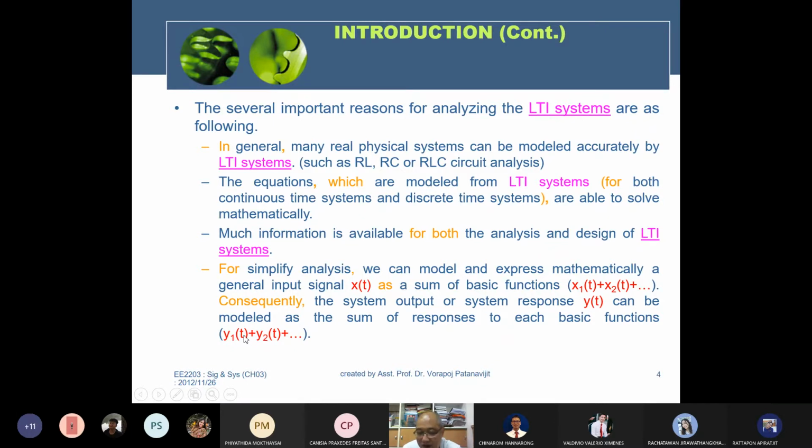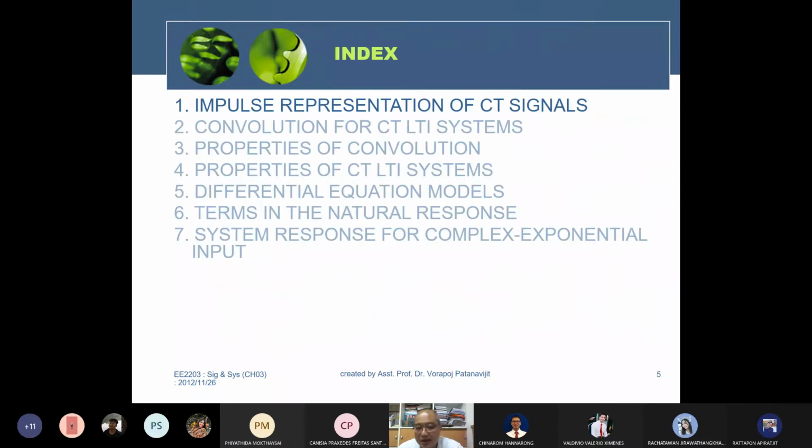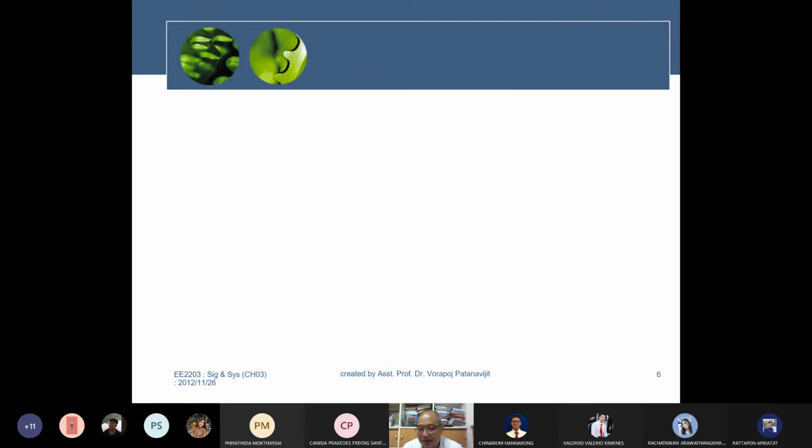Each band you can find the response. Instead of concerning a single signal with a wideband, you may be concerned with maybe 10 or 20 signals in very narrow bands. When the signal is already in a narrow band, the way to create the filters and amplifiers in that range is considerably easy. That's why. Now the next topic, the impulse response of the continuous signal.